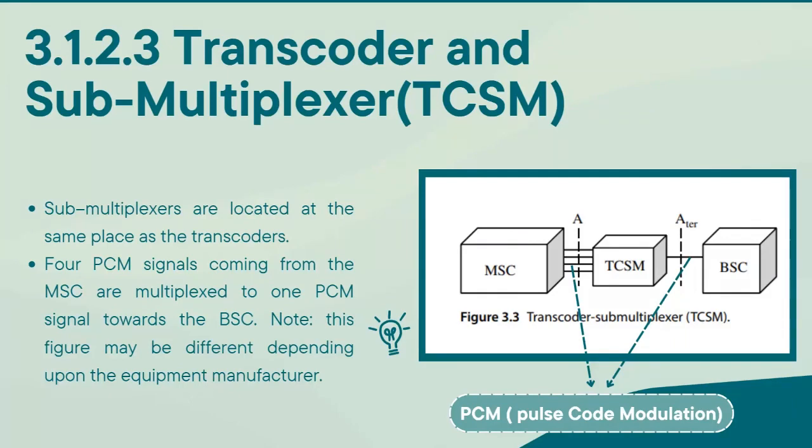But the question is, what is PCM or what is pulse code modulation? After we have been discovering this question, we have found out that PCM is a digital representation of an analog signal. It is also a technique used in digital communication systems to transmit analog signals over a digital transmission path by converting them into a series of digital binary pulse patterns.